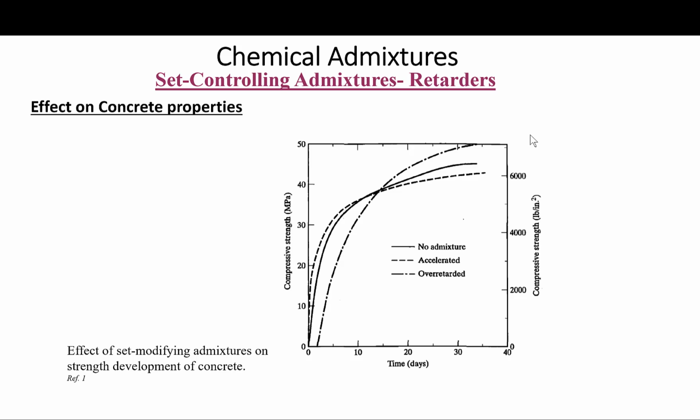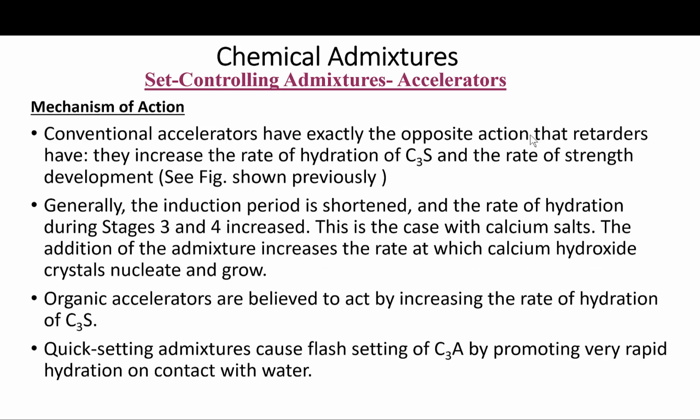So generally the induction period is shortened and the rate of hydration during stage 3 and 4 are increased. So this is the case with calcium salts. The addition of the admixture basically increases the rate at which the calcium hydroxide crystals nucleate and grow. Organic accelerators, on the other hand, are believed to act by increasing the rate of hydration of C3S.